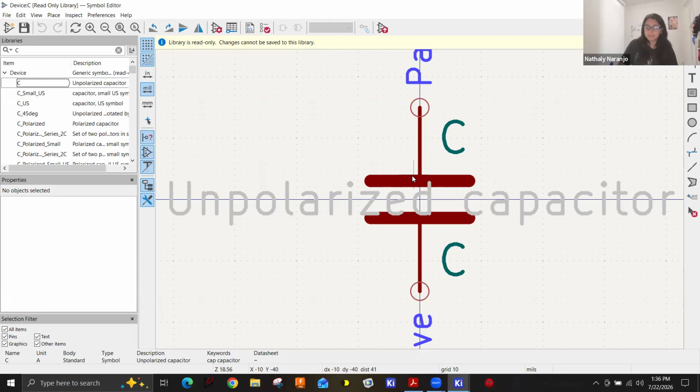Personally, when I'm trying to design the board, I don't want to have to make anything custom, but inevitably, the more complicated your system, you eventually have to do some custom stuff. Most of the stuff, like if you're doing all passive components, for example capacitors, resistors, and inductors, all of those symbols will be here. But when you start to invoke, like if I wanted a 555 timer, for example, have you heard of that chip before? Yeah. If you wanted that, they may or may not have it in KiCad.